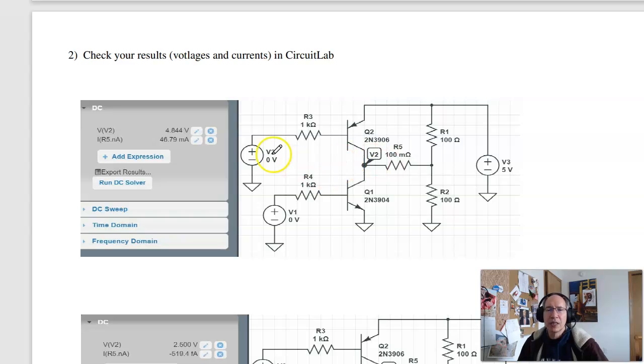But anyway, suppose I've got 0 volts coming in. That says the voltage is at 4.84 volts. Easier to write than to say. Okay, so that means that the PNP up here is saturated. When it's saturated, we assume the voltage drop is 0.2. 0.2 is kind of an arbitrary number. It's close to 0, but not quite 0. This says the voltage drop is actually 0.156 volts. Yeah, close to 0.2. It is saturated. And this one's off. So that matches up.